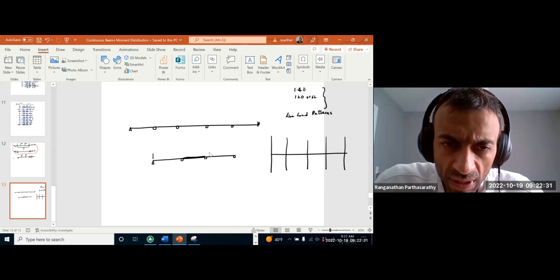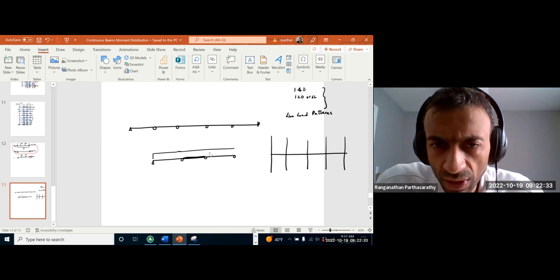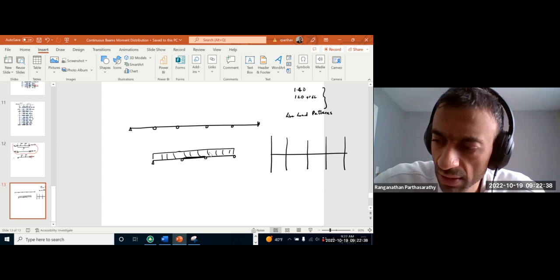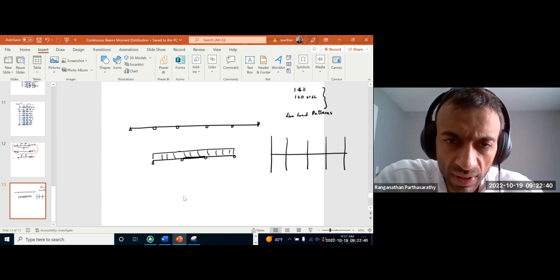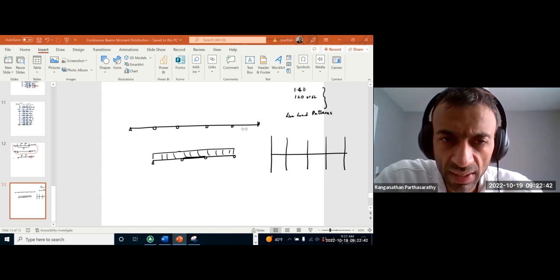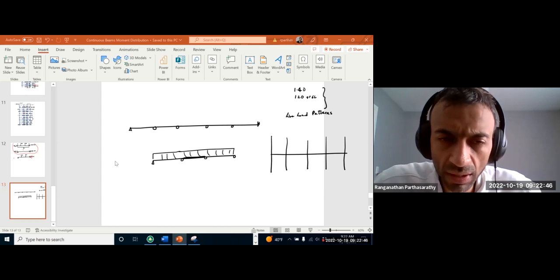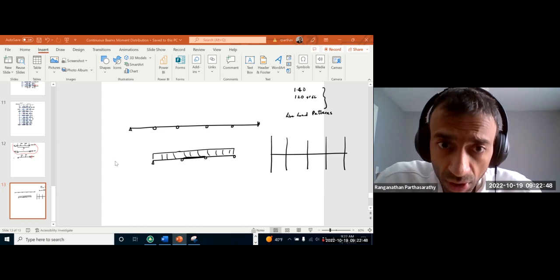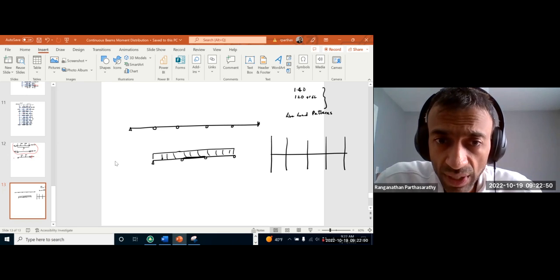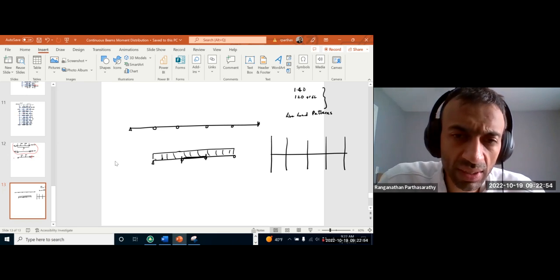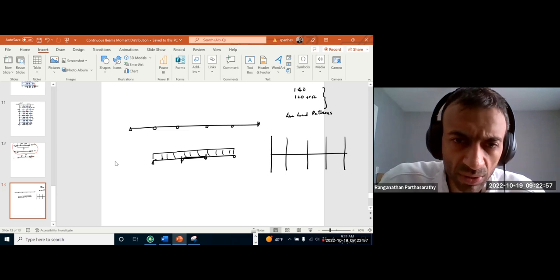Then if we put live load over the entire continuous span, that is not necessarily the combination which is going to give us maximum negative moments at these two supports. See, for example, if you put it this way, what will happen?